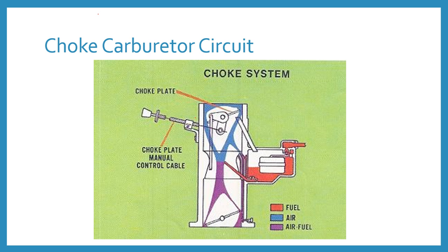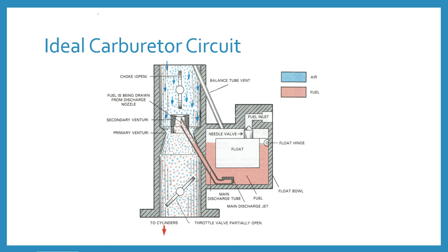Now coming to another carburetor circuit, which is known as the idle carburetor circuit. When the engine is in idle condition, the throttle valve is almost completely closed.